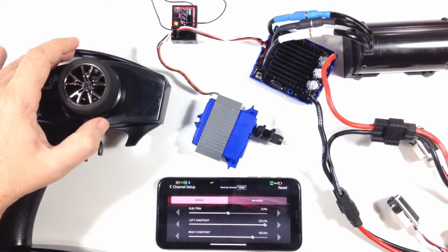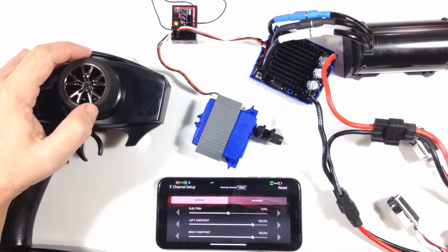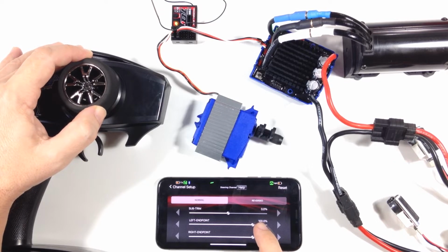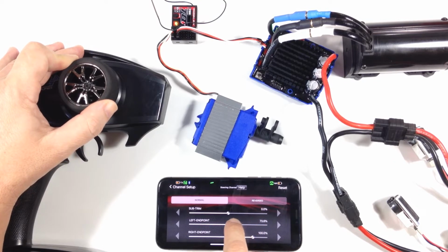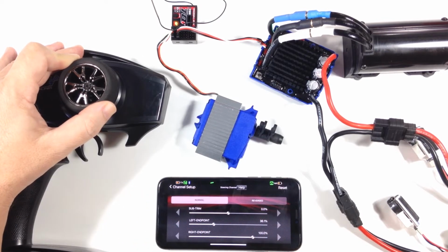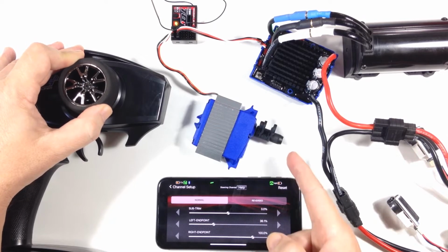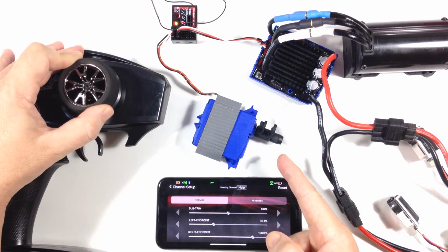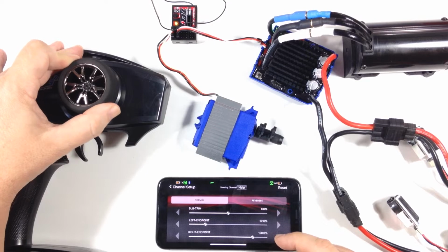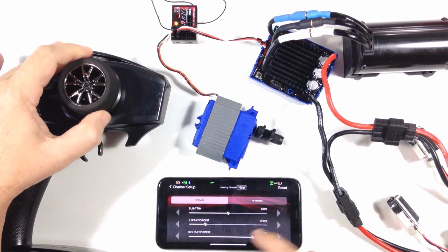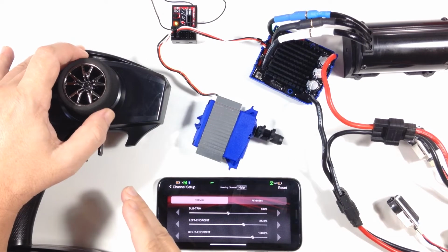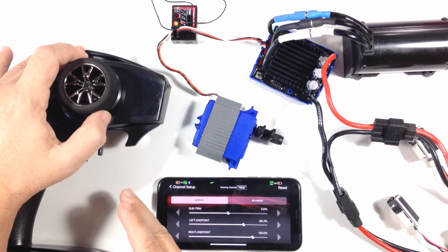So just reset that. Now here's the issue. When you would normally set endpoints for your steering travel in a car, so let's say full left and we'll drag that down a bit, what that would normally do is remap that travel as it is there, but as you can see, instead of remapping that travel, it just leaves a massive deadband at the end of the steering wheel travel. So you can see if you set your endpoint, you end up with deadband. What's happening is it's not remapping the reduced endpoint range to the full travel of the steering input.